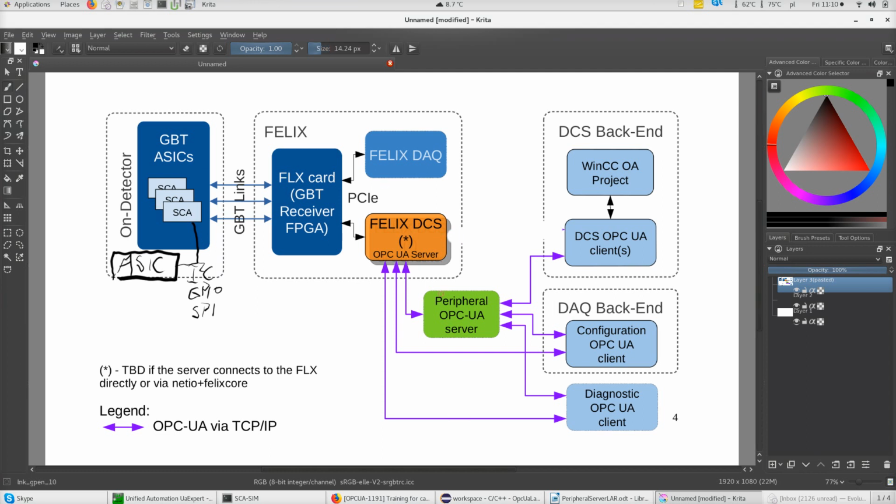So, just not to keep this picture too confusing, I'm going to erase this here. What we're trying to do is see how to create this green one. The starting point for you is, for sure, that you have deployed the SCA OPC-UA server, probably already configured with the config files. One thing to add: since I don't have your particular hardware and don't have access to it, but I still want to prototype, I will use a special mode called the SCA simulator.